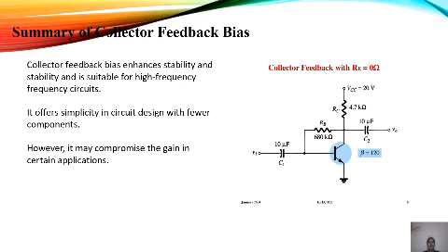Summary of collector feedback bias. Collector feedback bias enhances the stability and is suitable for high frequency circuits. It offers simplicity in circuit design with fewer components. However, it may compromise the gain in certain applications.